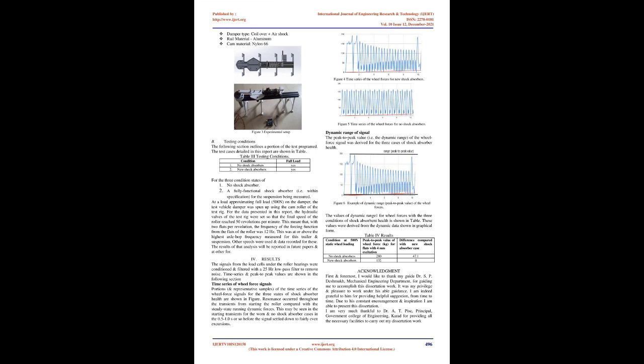Equation 7, where C is the damping coefficient, M1 is the sprung mass, Wn is the natural angular velocity, W is the angular velocity of unsprung mass excitation, Ks is the suspension sprung stiffness, R is the frequency ratio, W/Wn, and Ypk is the peak displacement of the unsprung mass. Equation 1 is rewritten to include the mass and the sprung mass acceleration, steady state response under harmonic excitations of amplitude Ypk, and can also be written as follows.